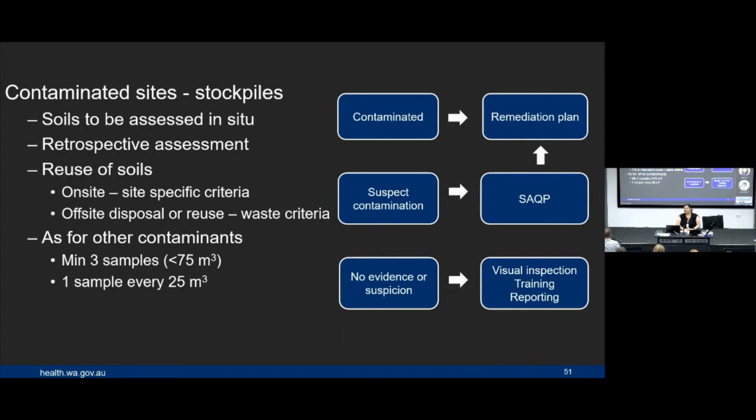Now, that doesn't mean that we necessarily want you to start creating and sampling stockpiles on contaminated sites. In fact, that's the last thing we want you to do. When you're doing contaminated site assessments, what we want is for you to not disturb the soils while you're assessing the nature and extent of contamination, because that's going to mess up your remediation and management plan potentially. So we do prefer that you assess your soils in situ as they were when you found them.